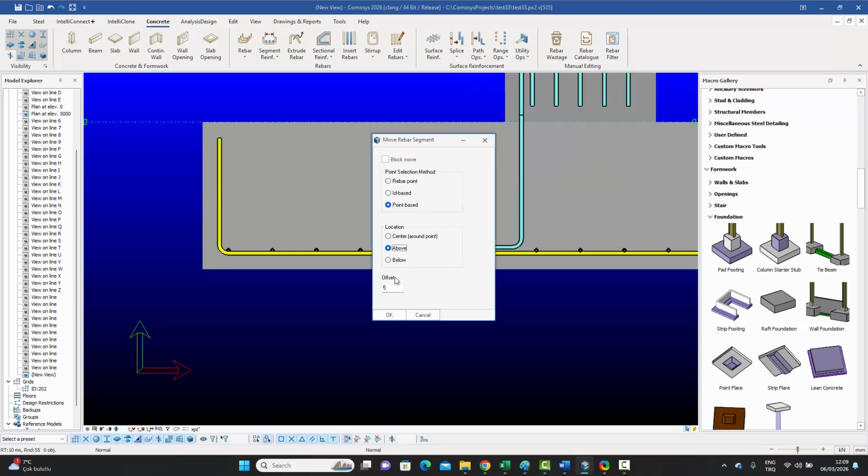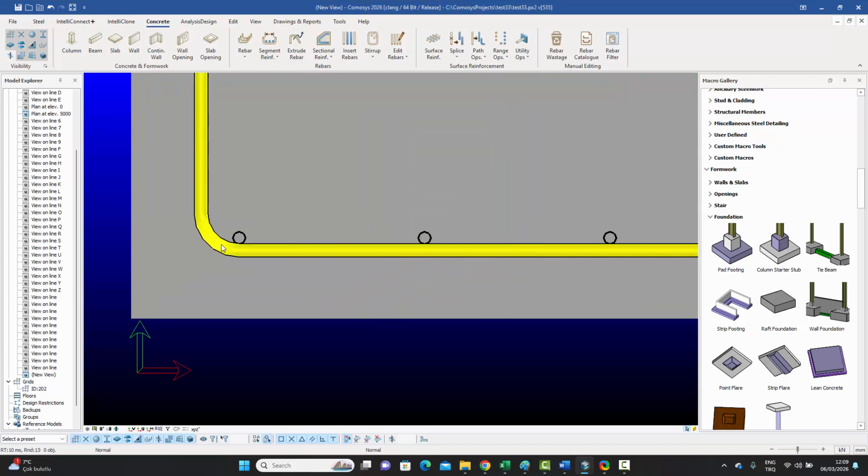So these are the settings. In that case, the setting for the offset would need to be such that we want it to sit exactly the way it's sitting over here. If you notice, it has a radius over here, and it's curling around. So the last point on which a rebar can sit is one radius away from that.